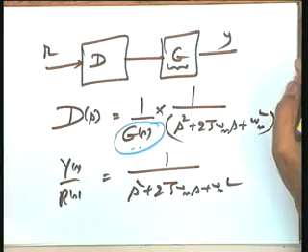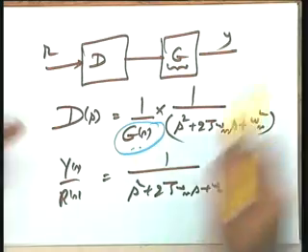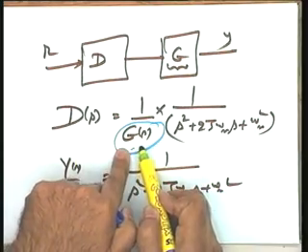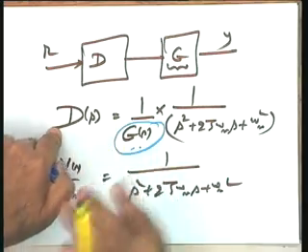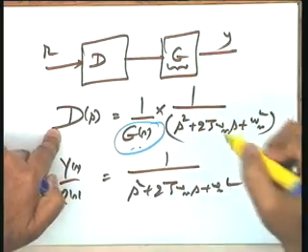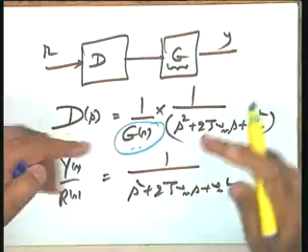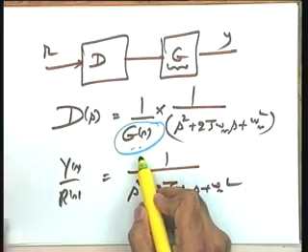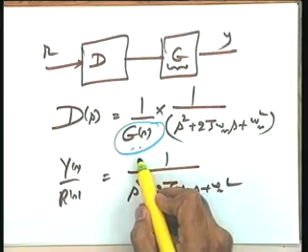So when you use a controller D(s) realized from G(s), it is not going to nullify the dynamics of the plant, though it is nullifying the dynamics of the model. Since there is always a gap between the model and the plant, this cancellation is possible with respect to the model only and not with respect to the plant.